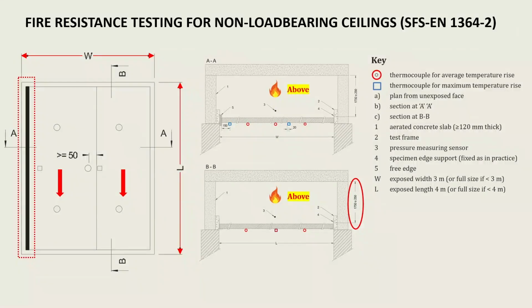Additionally, a gap of 25 mm to 50 mm shall exist within the free edge and shall be packed with a resilient, non-combustible material to provide a seal without restricting freedom of movement. The specimen orientation shall be designed to represent the most onerous conditions by arranging the more critical components parallel to the longitudinal axis. To measure average temperature for insulation criteria, 5 thermocouples shall be evenly distributed over the test specimen to monitor the temperature of the unexposed surface of the ceiling.